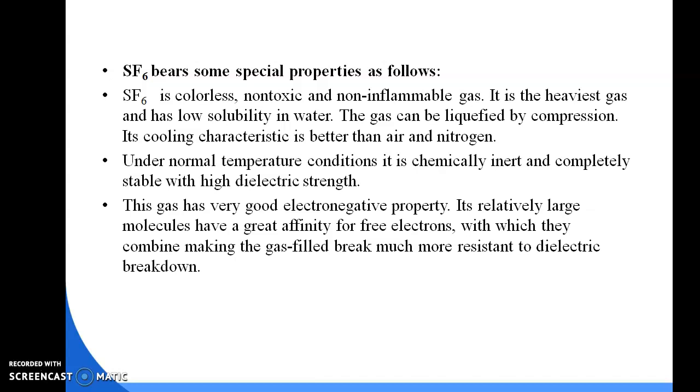This gas has very good electronegative properties. SF6 gas has an electronegative property. This is an important question that can always come in your exam: electropositive properties or electronegative properties. It is relatively large molecules that have a great affinity for free electrons, with which they combine, making the gas much more resistant to dielectric breakdown.